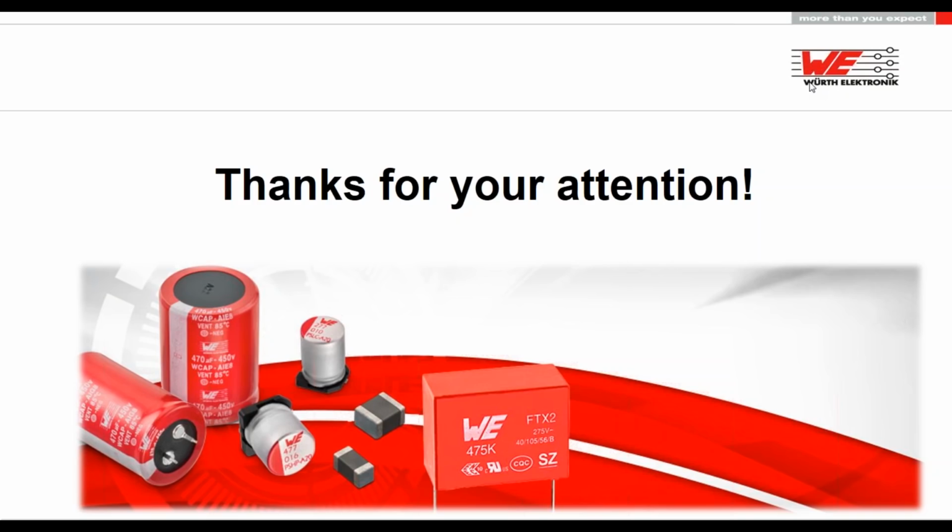And one question is, out of the capacitor types stated today, from my opinion, what would be the best? There is no best choice, because the best choice is really related to your application. You really have to consider what you want to go for. If you need a certain level of capacitance and voltage, normally you would go for E-caps, because they are quite cheap, they have a good range of capacitance, and you can go for a quite wide range of rated voltage. But you have to consider the aging.